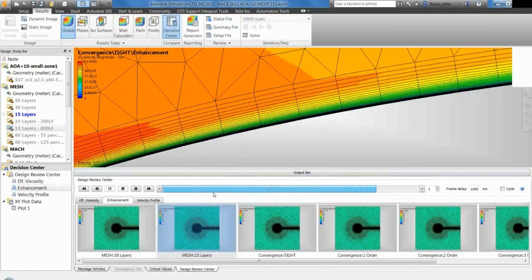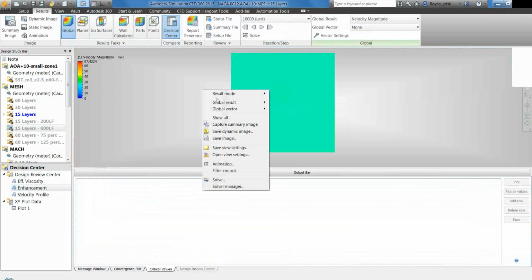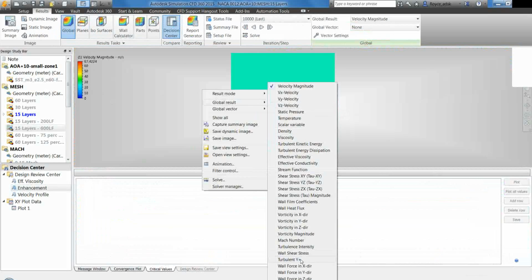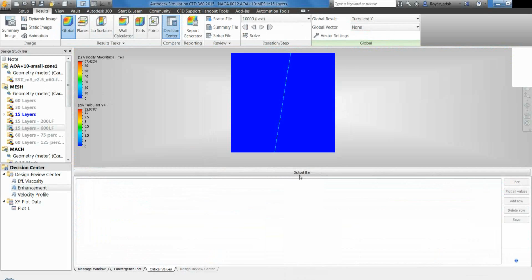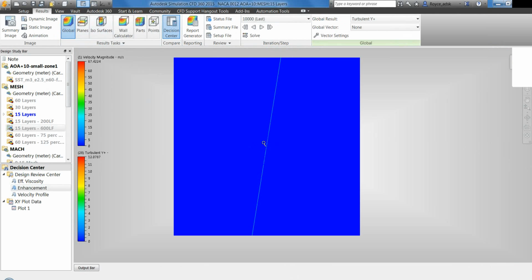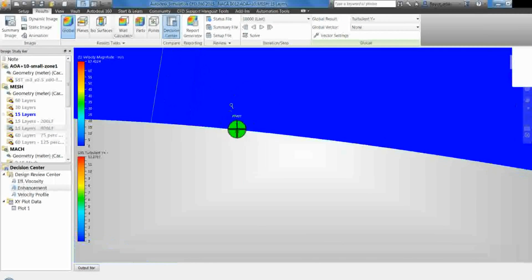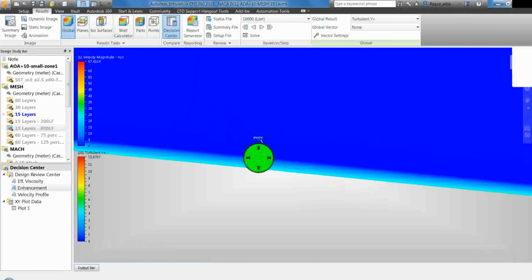Okay. Now, in terms of trying to assess, is this layer thick enough? Is it thin enough? Is this close enough to the wall, and so forth? In terms of close enough for that first layer, all you're really looking at there is, of course, your Y plus value. Of course, since these layers are so skinny, you really got to zoom in really far.